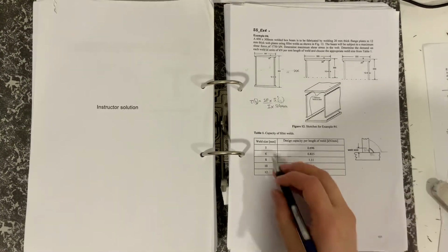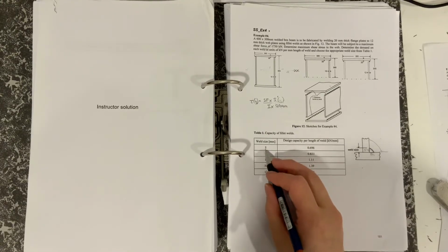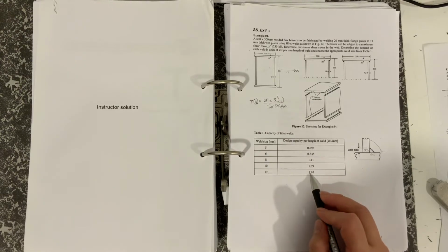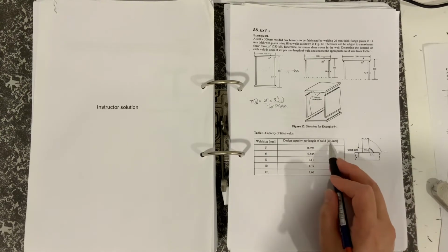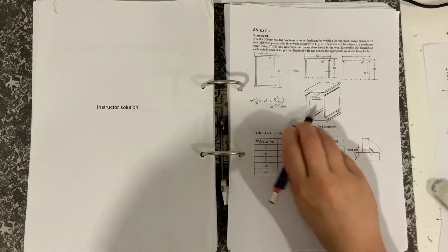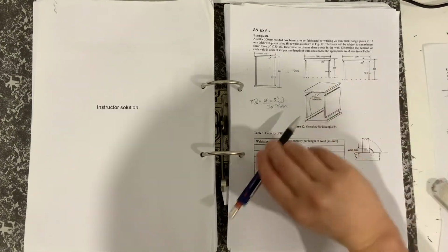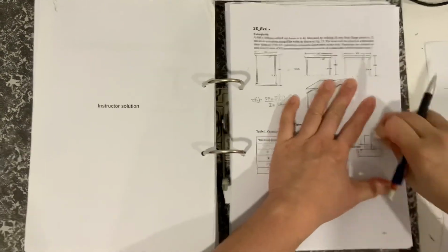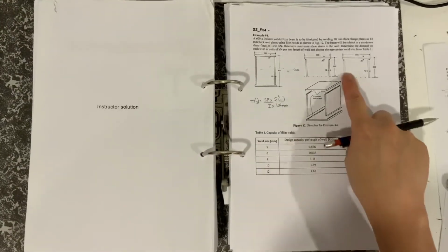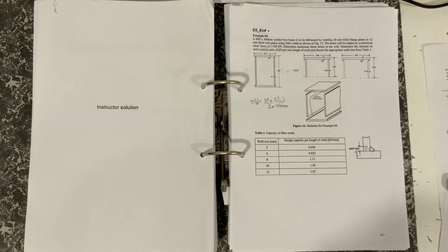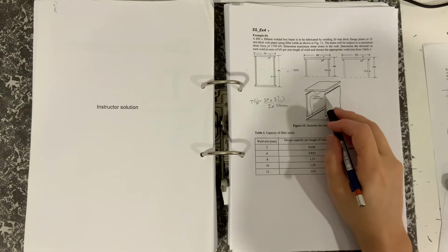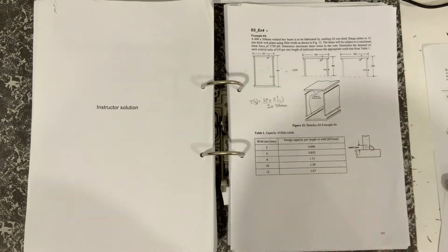Obviously, if you increase the weld size you increase the cost a lot, but the strength of the weld in kilonewtons per millimeter, millimeters being in that direction there, also increases by quite a lot. So this is clearly a shear flow issue. We're interested in the flow that's carried by each weld.